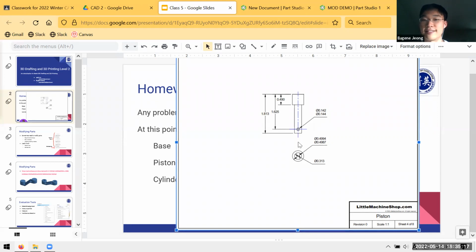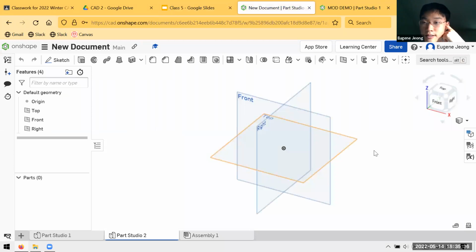If your eye was right there and you were looking into this view, this is what you would see. So there's a solid small circle, there's a bigger solid circle, and those are just the two rods that you're looking at. And then this dashed line that goes through it, that represents this hole. So it shows that this little hole is a through hole. So yeah, let's just go through it.